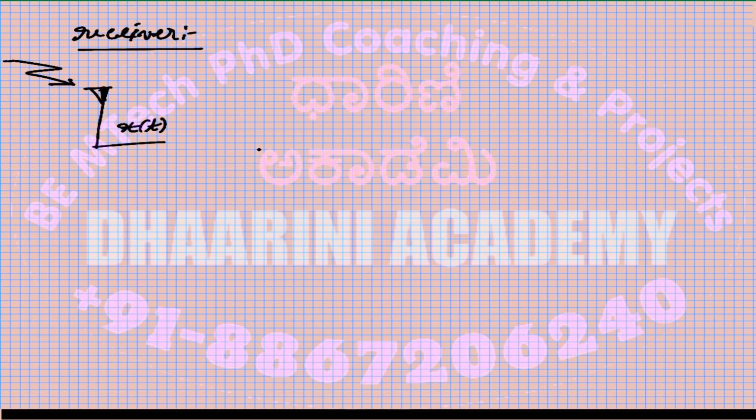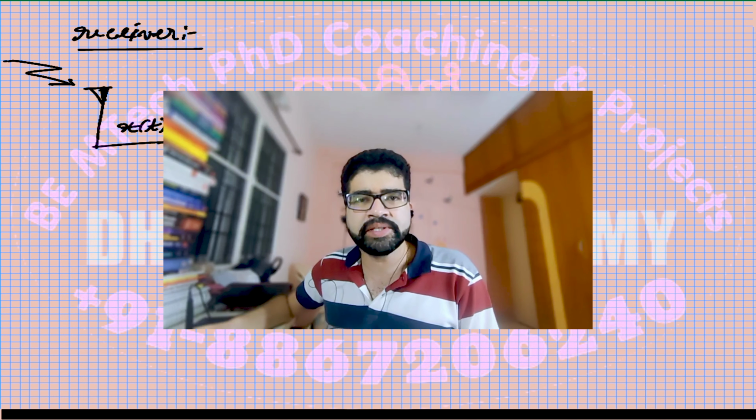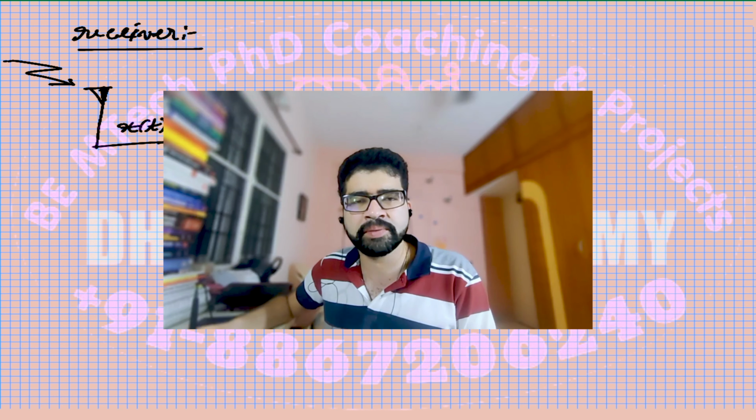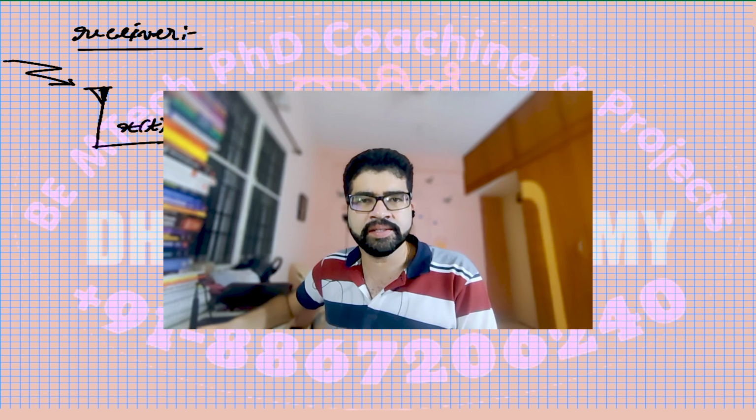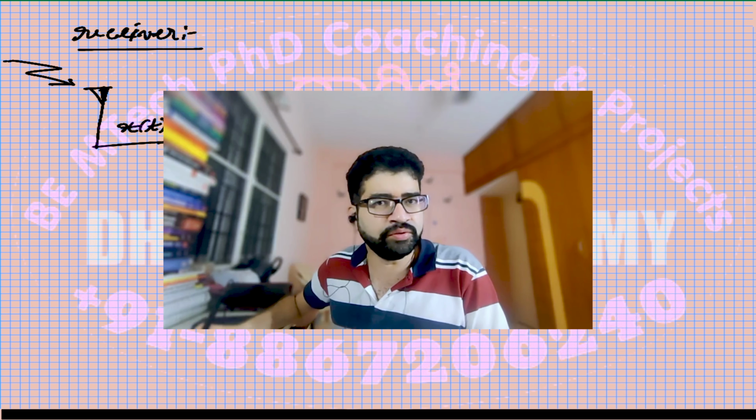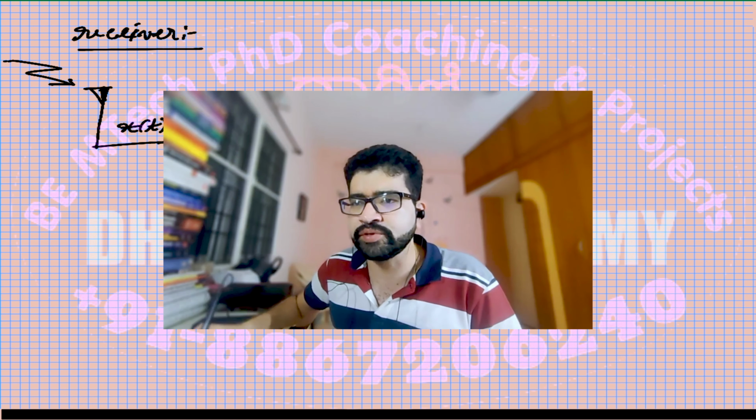Now, inside the first part itself, look at the difference. Previously, we had a multiplier circuit here, which used to multiply the received signal with the phi of t, the basis function. But now I don't know what the phi of t is, so I have to use a matched filter.